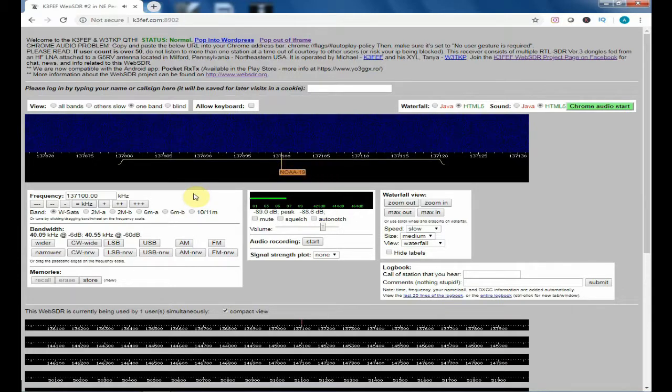Also make sure you don't have mute or squelch turned on so that you won't get the sound you need to record. You can record the audio, which is a really nice feature, and it starts collecting kilobyte sizes of the signal as it's being collected. Typically you would have about an 8 megabyte to a 12 megabyte file size for your satellite pass each time. When you hit stop, you can then download that file directly to your hard drive.